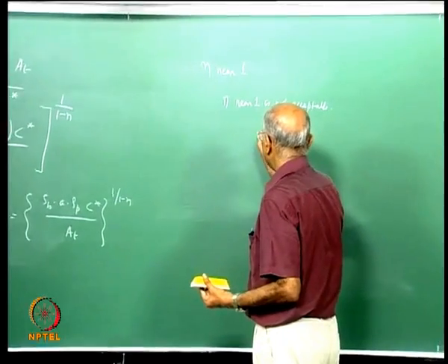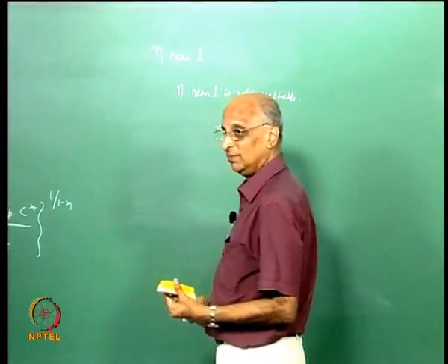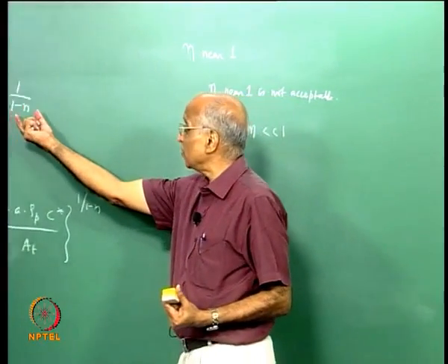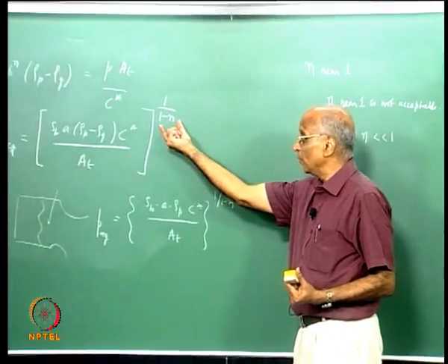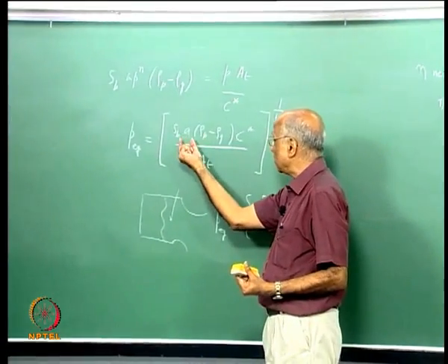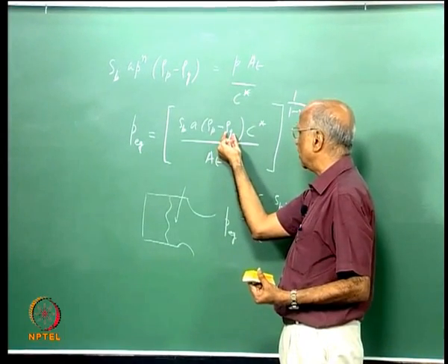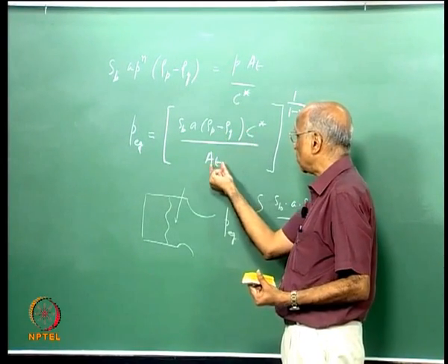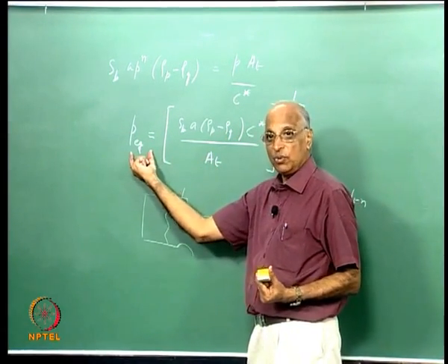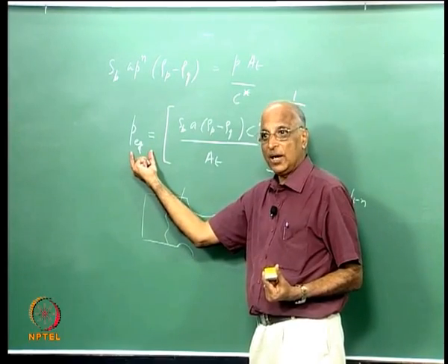That means n must be as small as possible, and that is better because I have a much smaller value, and therefore any changes in burning surface area while it is burning, some changes in the gas density while it is burning, some changes in C star or throat area should not lead to an explosion and an abnormally high value.